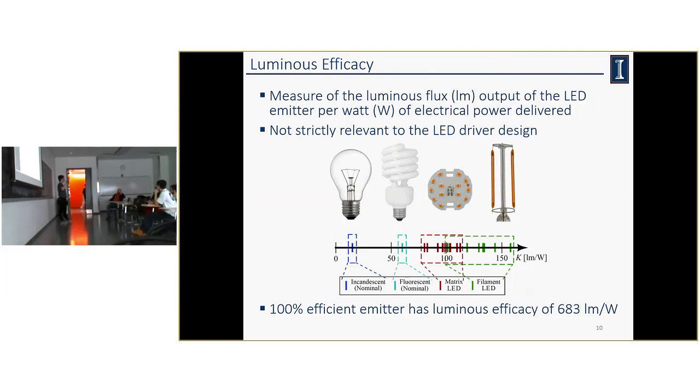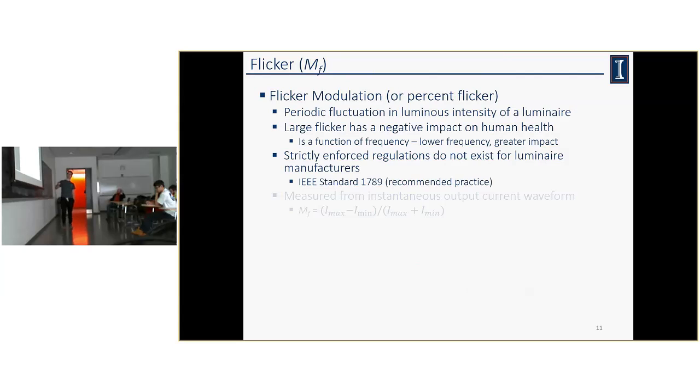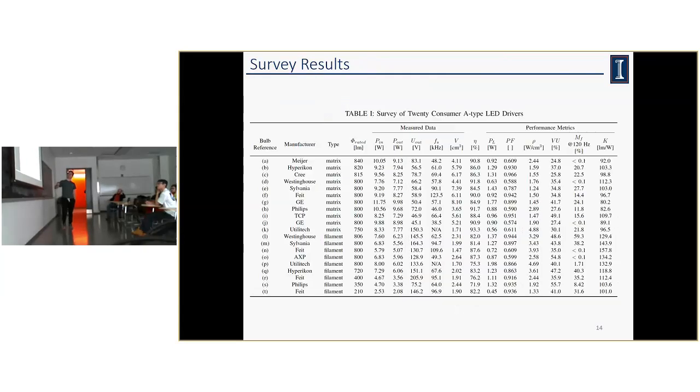Basically 90% of them are buck boost topologies. And a lot of that has to do with what the output voltage is going to be. Let's see, do I have data for that? Okay, so this column right here is the output voltage. And the AC is obviously 120 volts RMS, so this decides whether you have to boost or you have to buck boost, right?